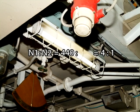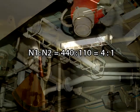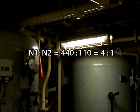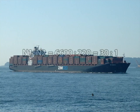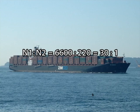Let's now look at the voltage used for lights on board a ship. When the generator voltage is 440 volts, a voltage of 110 volts for inboard lights can be obtained by setting the ratio of primary turns to secondary turns as 4:1. The number of large-size ships offering generator voltage of 6,600 volts has been growing. A transformer turns ratio of 30:1 is employed to convert this voltage to 220 volts, which is compatible with the engine room pump.